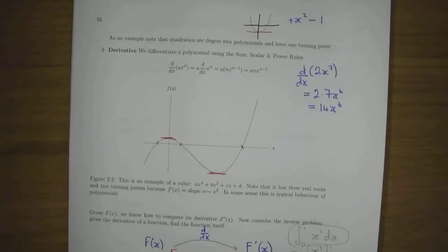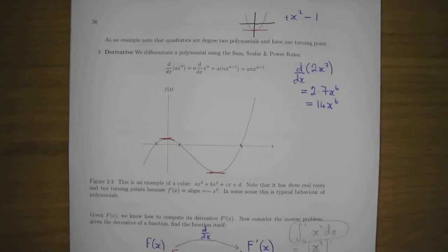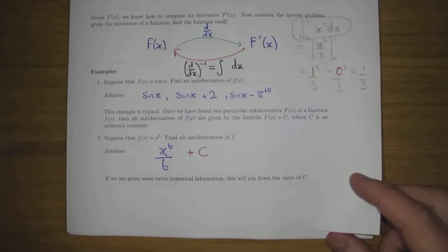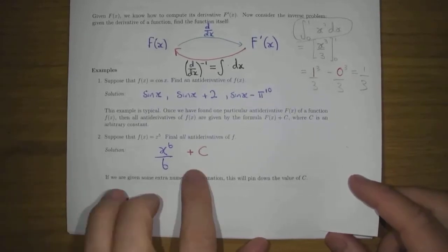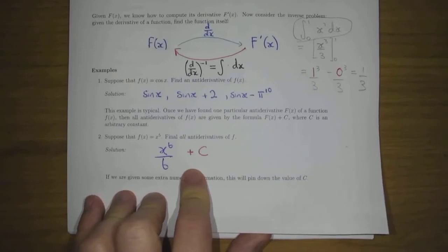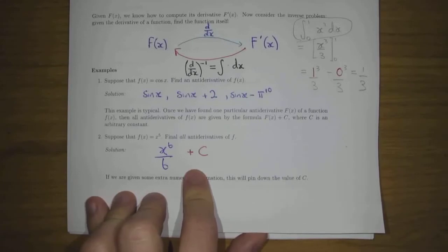Now the information for us will consist of knowledge about the beam. Is it a simply supported beam? Is it fixed ends? Is it cantilevered? The constants we're going to come up with, the extra bit of information, will be given by that. In fact, we're going to have 4 constants and they're all going to have a physical meaning.